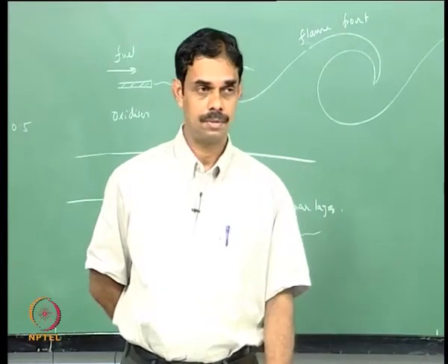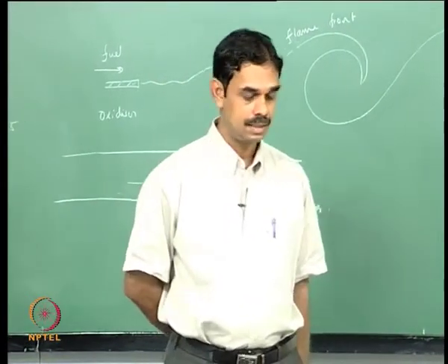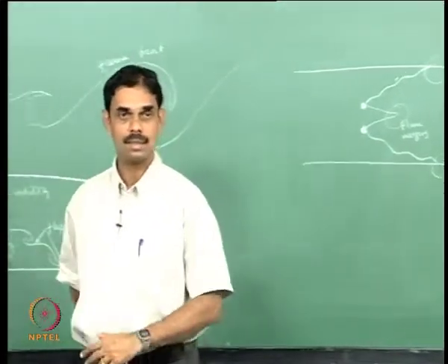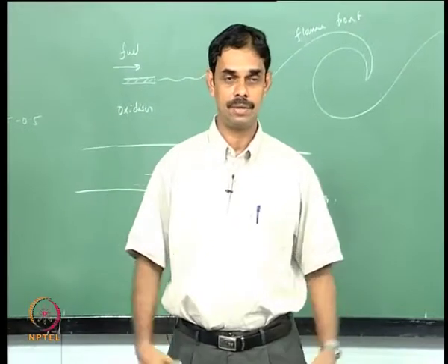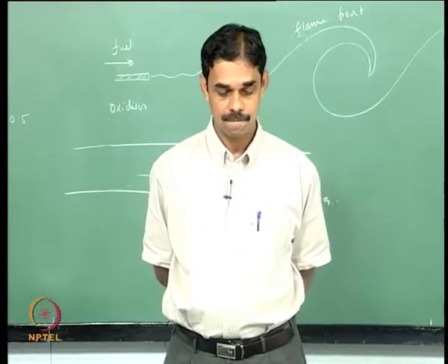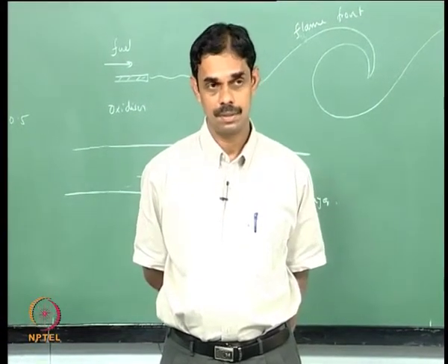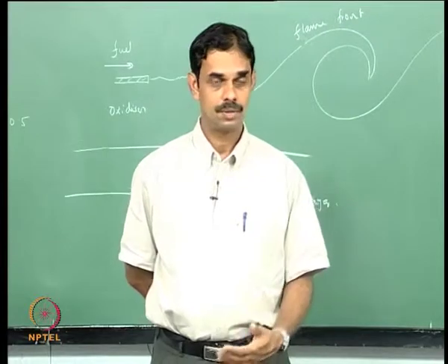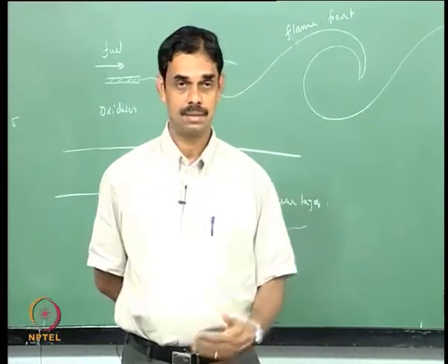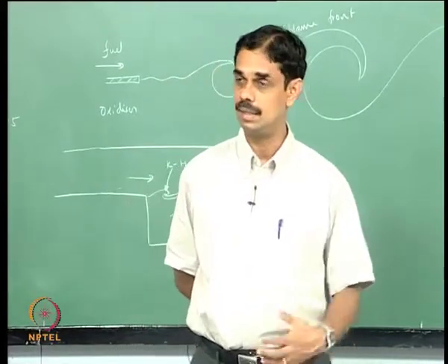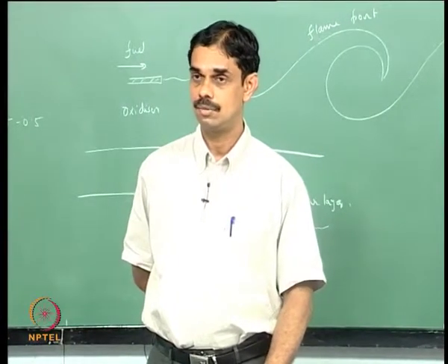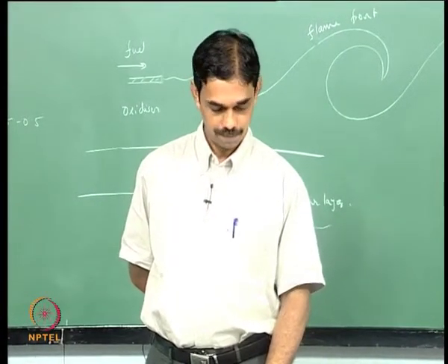So you will have in any case some kind of unsteady heat release rate, but in such combustors the flame will be somewhat long, and there is a possibility that the entire flame may not have the same driving or damping characteristics. Some parts may drive and some parts may damp. So whether oscillations are excited or not depends on whether the net driving is more than net damping or not. Everything goes by what Rayleigh said. If the heat release is in phase with the pressure oscillations, you have acoustic driving. If they are out of phase, then you have acoustic damping.